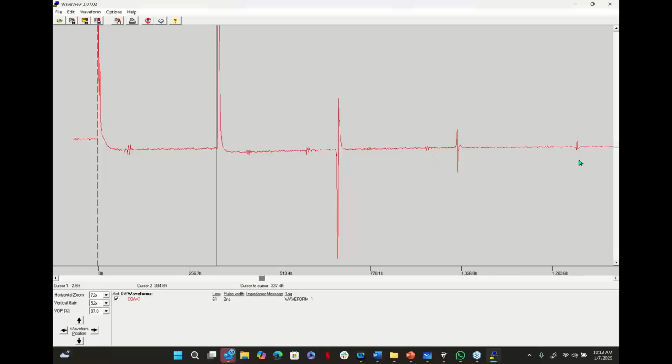What are these called? They're called reflections or ghost reflections. The reason ghost reflections happen is because a TDR is sending out a pulse. What's a pulse? Well, a pulse is a certain burst of energy, and it's sending it out several times per second. How many times per second? Well, however many cycles per second the pulse width is based on, right? So all of these other reflections are just echoes, echoes, echoes of that original pulse. Okay, it's just residual leftover harmonics.